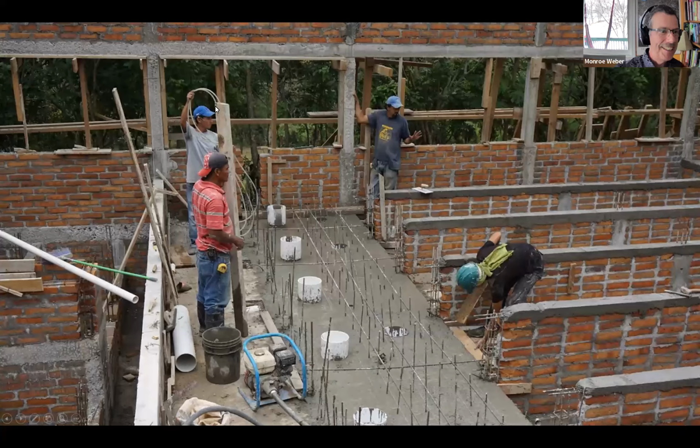And I'm curious, has anybody seen construction in other parts of the world where you don't actually use a theodolite to do leveling, but instead you use a water hose? It turns out this is a pretty accurate way of doing it. That water hose is transparent, so you can see the water inside the hose, and you set the hose up so that there's a little bit of air at each end of the hose, and you can use the water level in that hose.